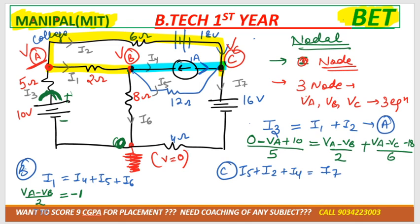Now see I4, the current source is given. The I4 direction and the current source direction are opposite, so we can directly take it as -1. If a current source is given, then we don't need to convert it in terms of V by R, we can directly take the value. So I5 is how much? VB minus VC by 12. I6 is how much? I6 is moving from VB to 0, so VB minus 0 by 8. Here I7 is how much? It is moving from VC to 0, so VC minus 0 minus 16 divided by 4.